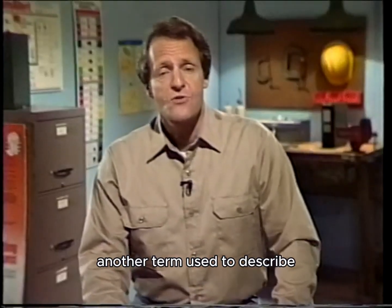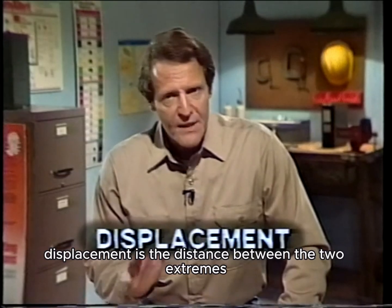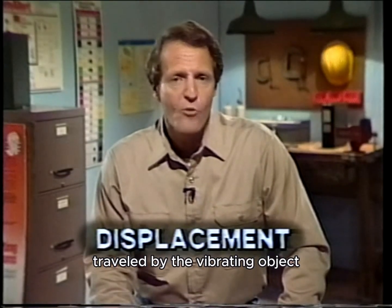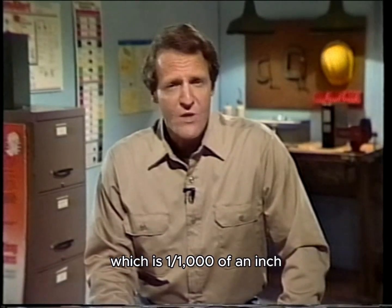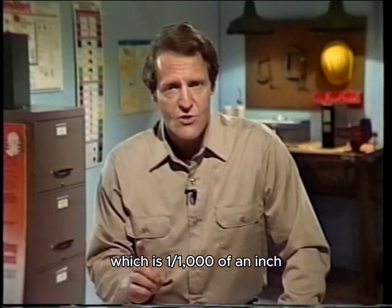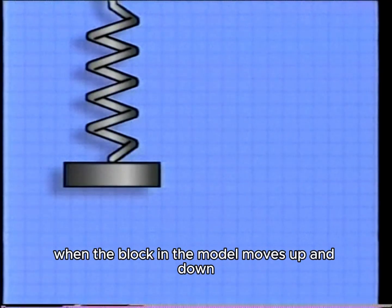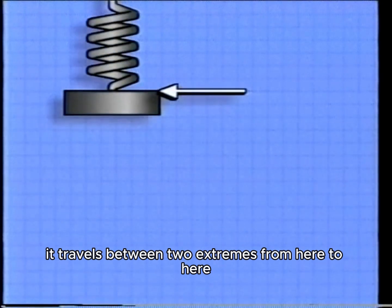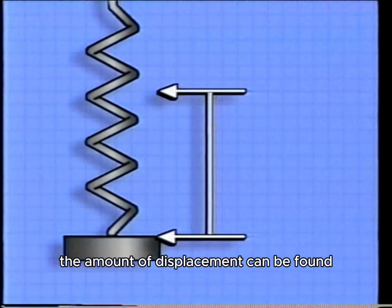Another term used to describe certain features of vibration is displacement. Displacement is the distance between the two extremes traveled by the vibrating object. Displacement is usually measured in mils, which is 1/1000th of an inch. For example, when the block in the model moves up and down, it travels between two extremes, from here to here. By measuring the distance between those 2 points, the amount of displacement can be found.